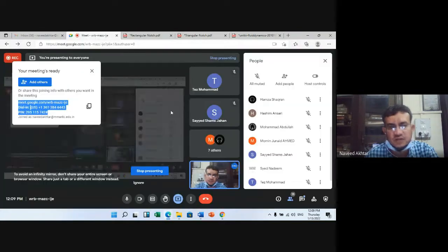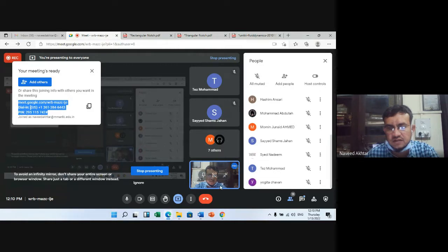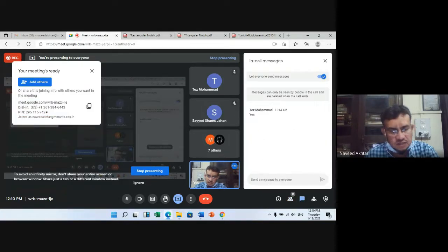Performing means you have to see the video lecture, write down the readings, apply Chezy's formula and Manning's formula, and find out the constant of Chezy's formula and the constant of Manning's formula. The constant for Manning's formula is n, and for Chezy's formula is C. That part is already covered in the theory class. If you see the video lecture, you will understand. Also you can see lectures number 44 and 45 to understand Chezy's and Manning's formulas.